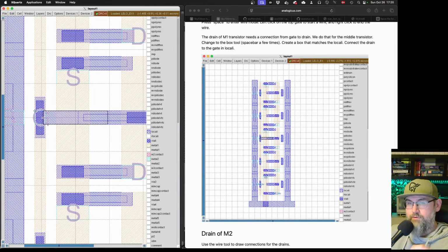It's also possible to generate something called Frenkel pairs, which is, you should think of it like, usually in an amorphous silicon oxide, you have a mix of silicon and oxygen. It's sort of different places of the atoms. The oxygen atoms can actually wander. They can sort of break out of the structure and get lodged in places they shouldn't be.